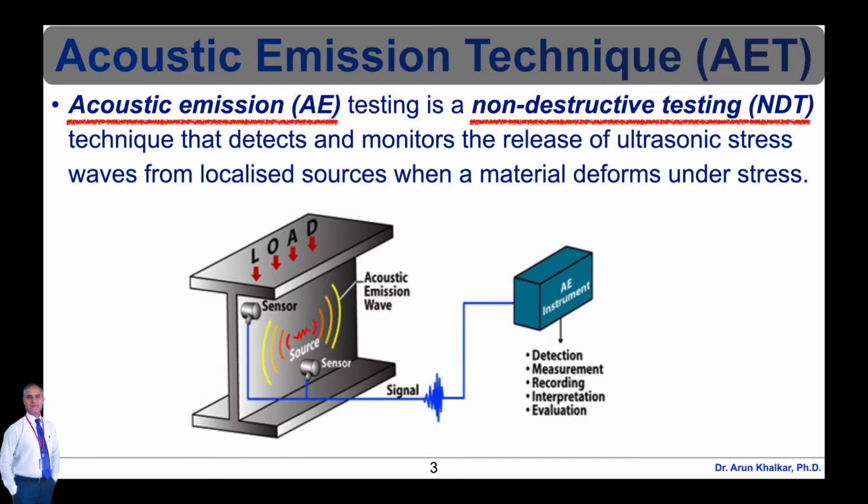Acoustic emission can be thought of as tiny earthquakes that occur in the material. The technique globally monitors a component for defects, allowing large structures and machines to be monitored while in operation with minimal disruption, unlike destructive testing.